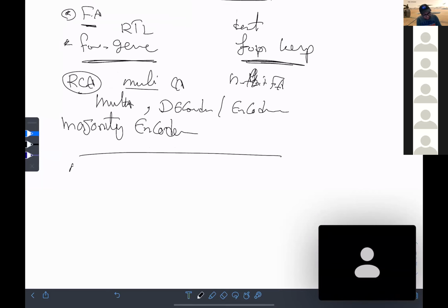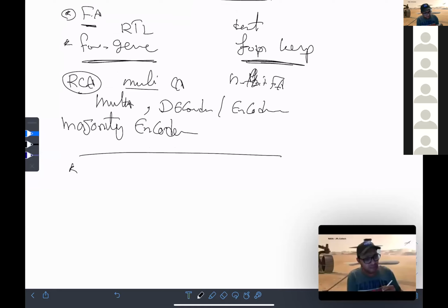There are no registers. At the end of the day, with the gates we have, we can just build a latch, right? And the tool we are using defines what a flip-flop is. So if we build a custom circuit, it might work. But in the context of Vivado, it might consider this purely a latch and just completely remove it. Does it make sense?